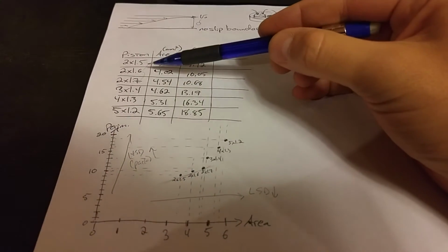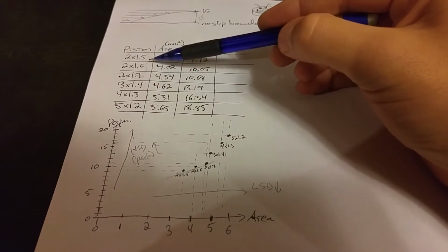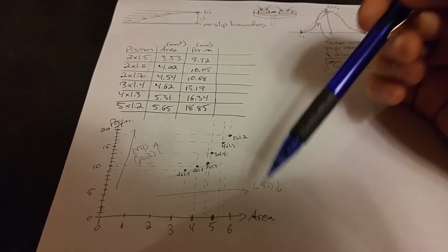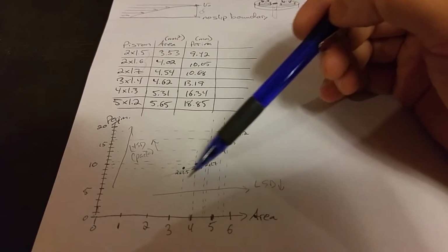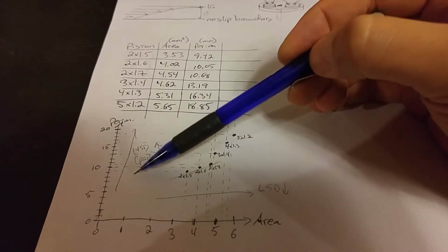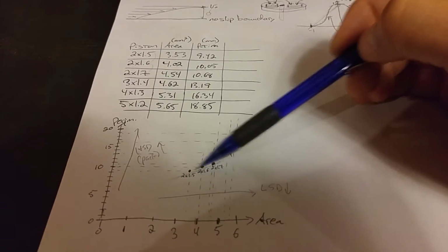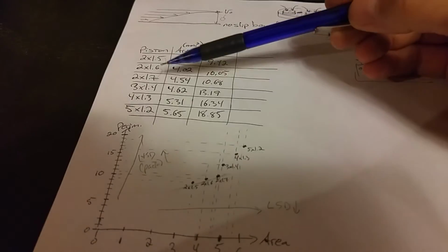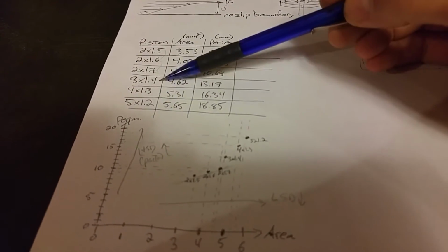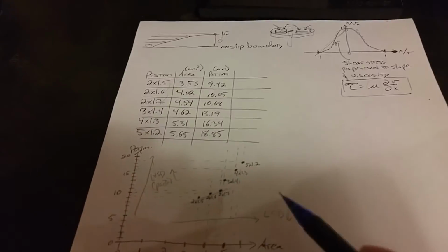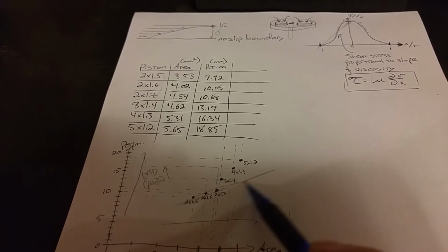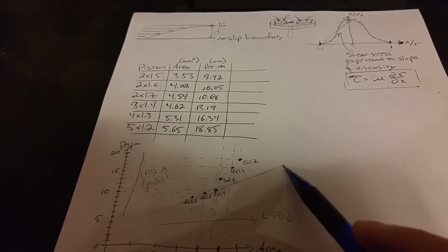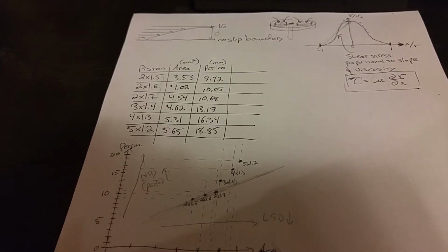So as I go to larger piston holes, I have smaller low speed damping, so it gets effectively softer, and I have more pack, more high speed damping, along this curve. But then I start changing the number of holes and the size of the holes at the same time. So instead of moving along this curve, this would be sort of my two-hole curve here, if I just went infinitely back and forth along this curve.